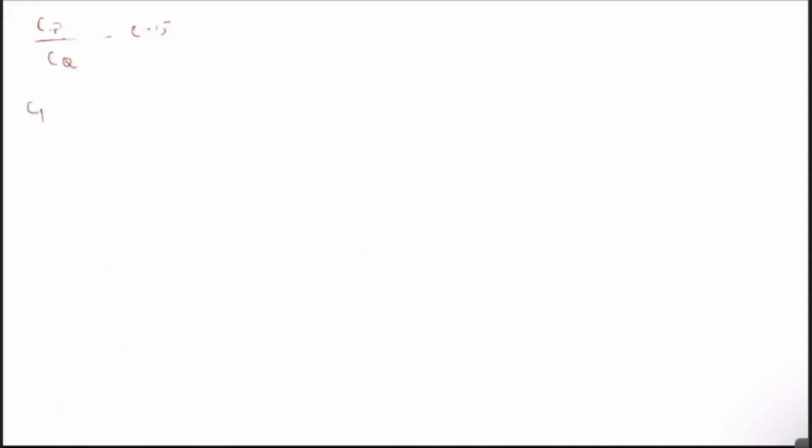So this is a constant volume system. So we can write Cp and Cq in terms of their initial concentration as Cp is equal to Cp0 into 1 minus Xp, and here, since we have equated it at equilibrium, it will be Xp equilibrium. And Cq is equal to Cp0 into Xp at equilibrium.